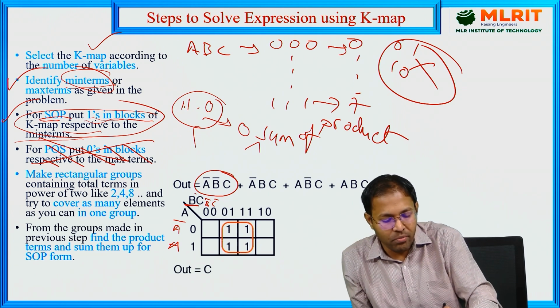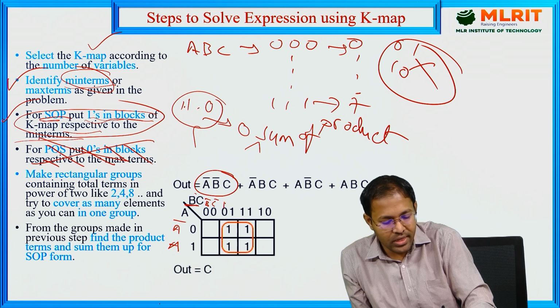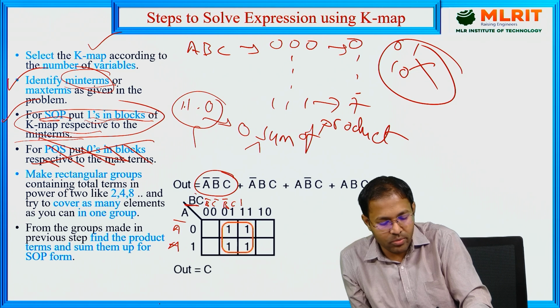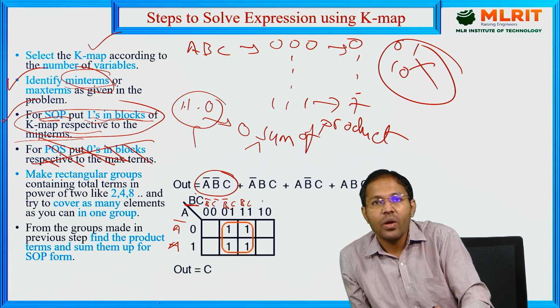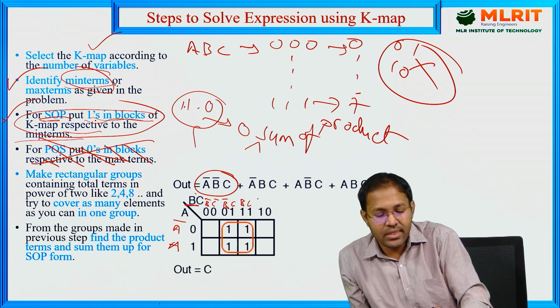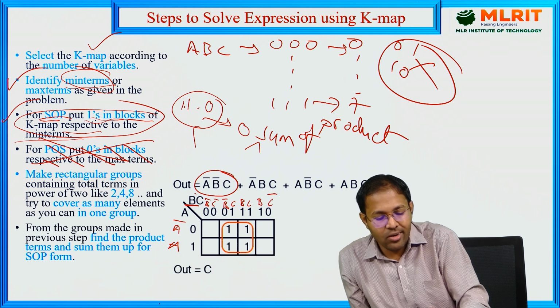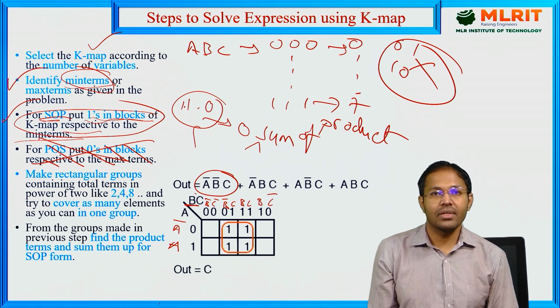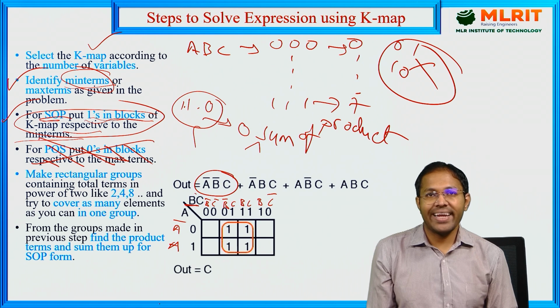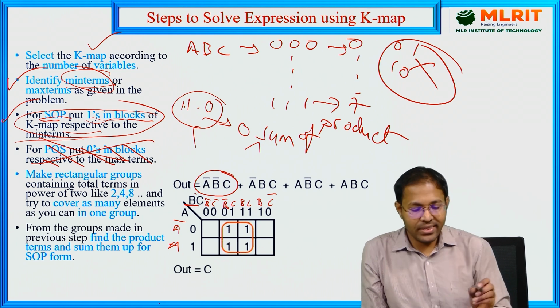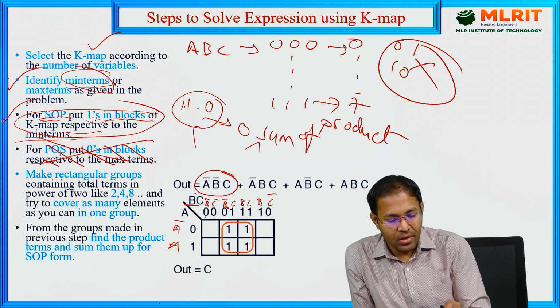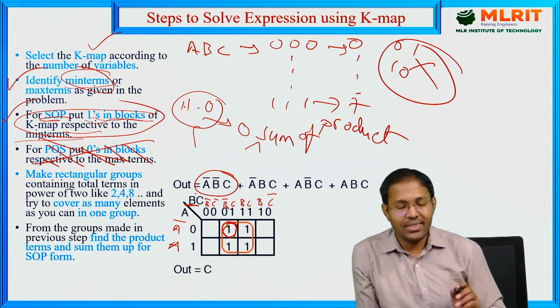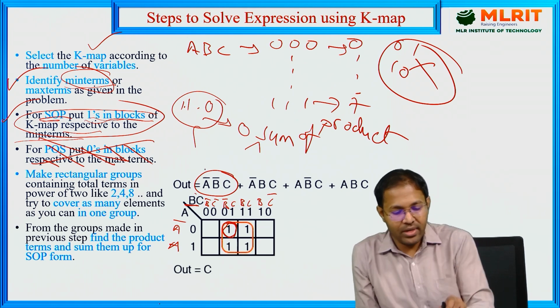Likewise true form. The first variable here is 0, so we have to take it in complementary form, and 1 we have to take in true form. Again 1, 1, so both in true form. Again 1, 0 means B in true form, C in complementary form. Now we need to locate A bar, B bar, C. So let us see A bar, this row, then next B bar, C means 1. That's the reason we are writing a 1 there corresponding to this.